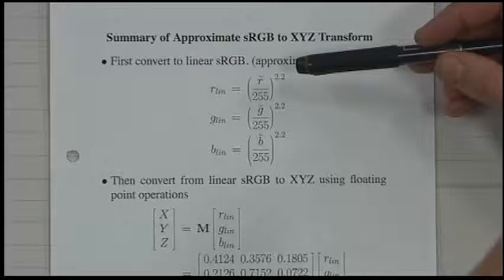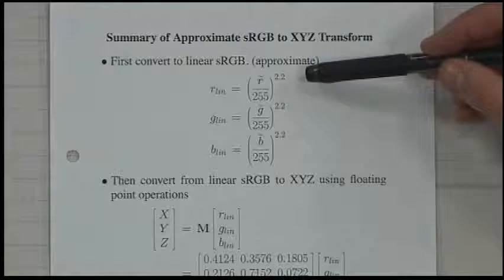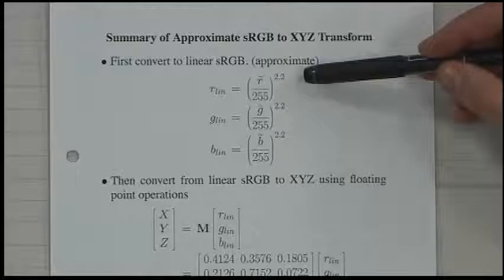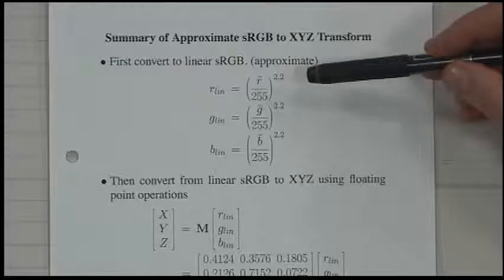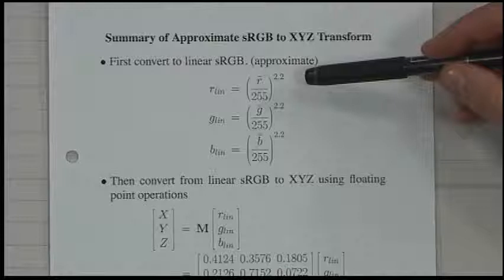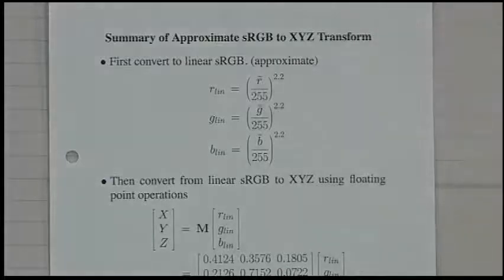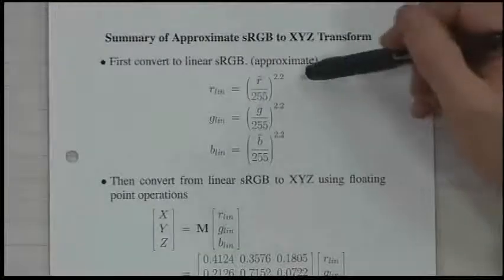If you're doing it with analog devices, like you use diodes and so forth to approximate a power law relationship, it's hard to do that extremely precisely, particularly as the power gets larger, because the derivative of the function is very large. If you're off a little bit, the function's approximation is quite poor. So I think that was another reason people use 2.2 rather than 3. In any case, 2.2 is kind of the standard.